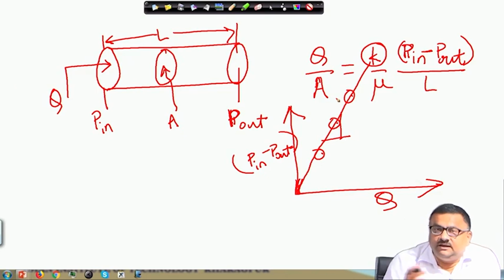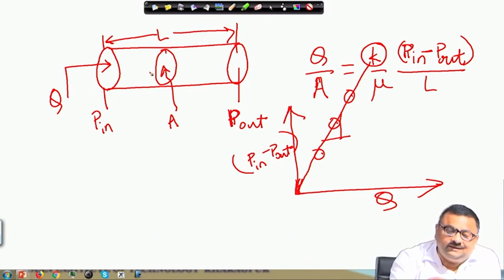If someone has a porous block, suppose somebody has pulled out a core from a reservoir, then naturally it has to be put inside a core holder using a rubber sleeve, so that no flow can take place through the sides of it. So, all flow will be directed through the core, or there could be some kind of wrapping used, where there would be no flow coming through the sides, only a unidirectional flow from inlet to outlet.